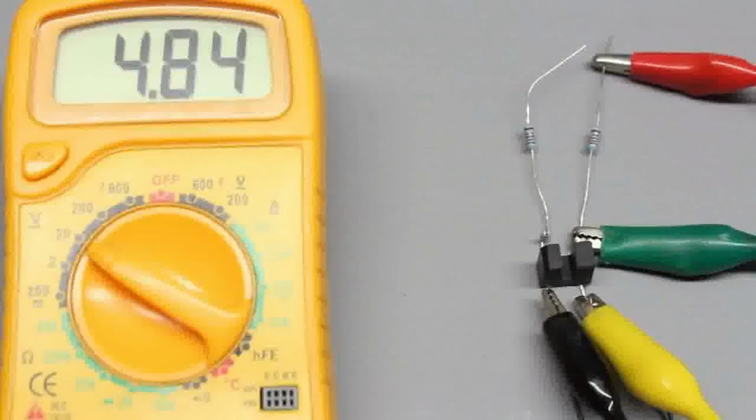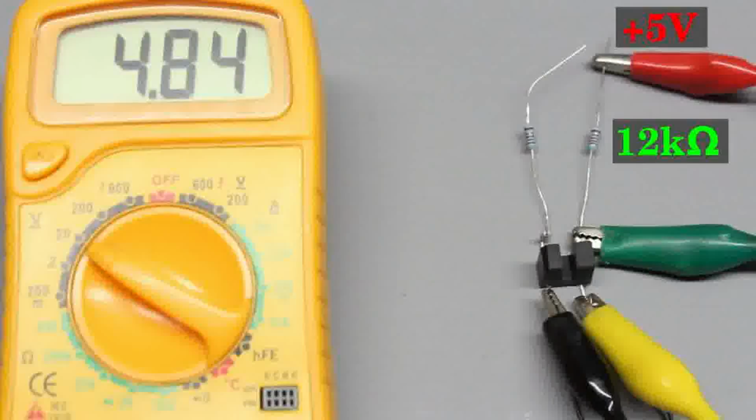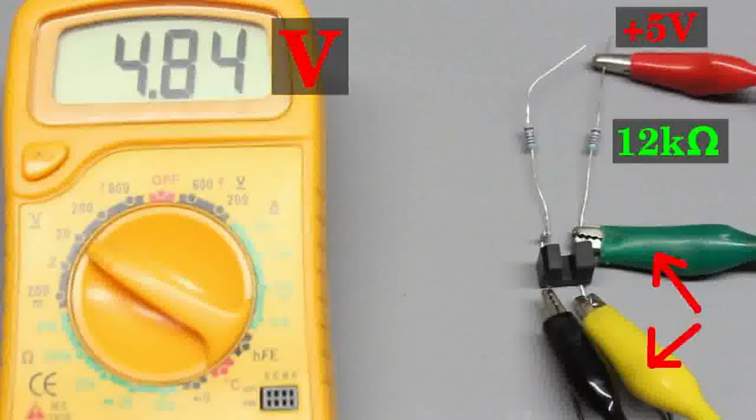Next thing to be done is figuring out the polarity of the receiver side. We need a second resistor, also having a value of approximately 10 kiloohms. That series resistor is connected to the phototransistor as well as to plus 5V. First, the upper pin of the phototransistor is connected to plus 5V, the lower pin is connected to ground. With the multimeter, the voltage across the phototransistor is detected.